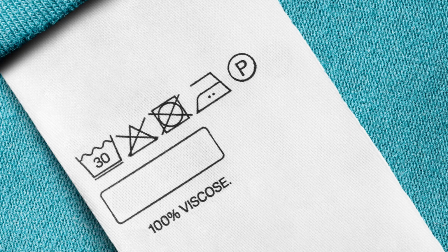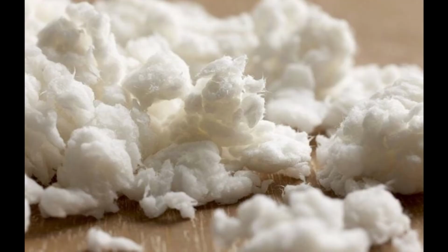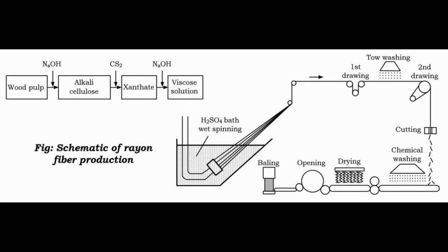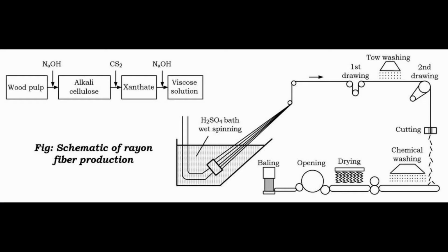The question is how wood pulp is transformed into viscose yarns, so basically into garments, guys. It's quite easy. You take the wood pulp or cellulose pulp and you dissolve it in sodium hydroxide, caustic soda. And then from the alkaline bath, you take that to the carbon disulfide and then you add still more sodium hydroxide. Then from a sulfuric acid coagulation bath, you have the spinneret to spin all the coagulation into the yarn into cones.